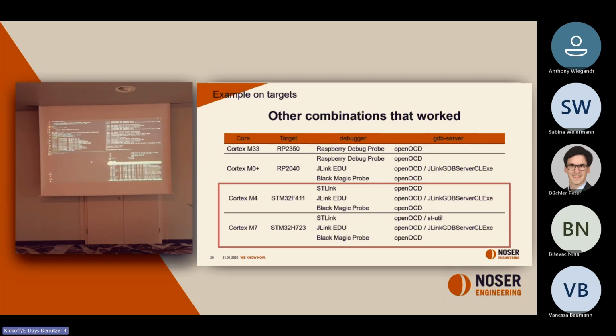I still have my full development environment here, and I go to binary. I just have to run arm-none-eabi-gdb with the ELF file. It's ready. And now I don't have to start the GDB server, as said. I just have to look at the device.